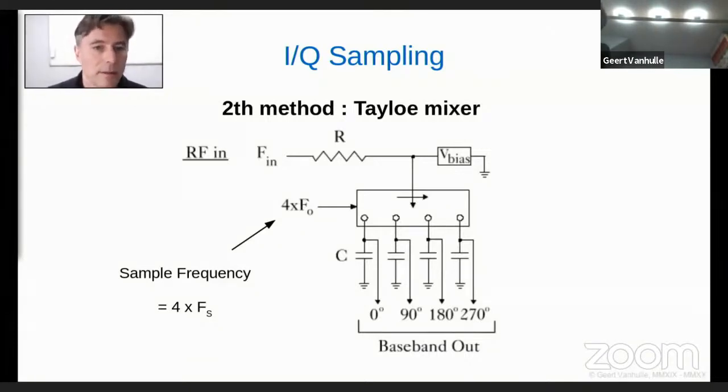There are typically 4 of these switches inside of these chips. So what you see here could actually be a 4066 CMOS chip that we feed with our RF signal. Now what we will do is we will close these switches successively, and create a switch with 4 outputs.